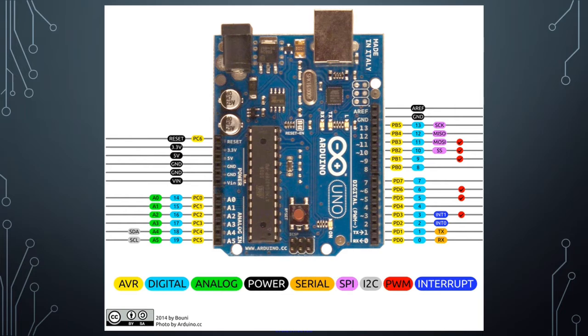Now let's go through our pins. So you might notice along the bottom of the screen, we have some different things mapped out here. This is kind of our key at the bottom, and this just tells us the capabilities of each pin. So every pin, every place that you can poke a little wire or component into, cannot perform every function, and that's very important to remember and to refer back to your pin map when you are constructing your circuit to make sure you're using the appropriate pin.